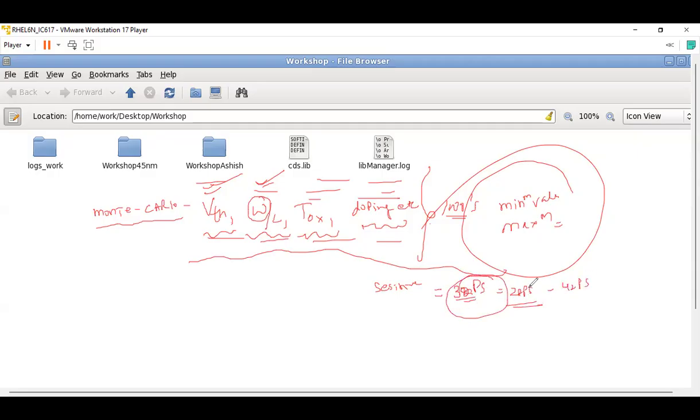You will say that my device may have 28 picosecond, may have 42 picosecond, but there is a maximum possibility of 31 picoseconds. That will show when you give a statistical plot and you get a plot like this, and there you get a certain value here at 31 picosecond. Then you say that I can have 28 picosecond, I can have 42 picosecond, but there's a maximum possibility of getting 31 picoseconds. That is why Monte Carlo simulation is important. And remember, it is computationally intensive.